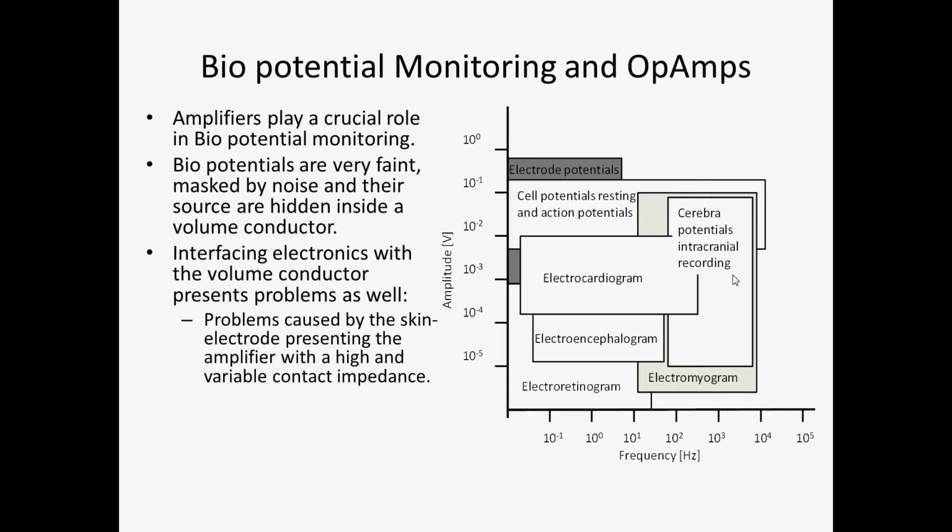Probably you're too young and you've never come across this issue, but with very old audio amplifiers, when you were connecting the microphone jack or the headphone jack, they were spiking, and that spike could actually destroy the speaker. So the recommendation was either to turn off the amplifier or put the volume down at the minimum.